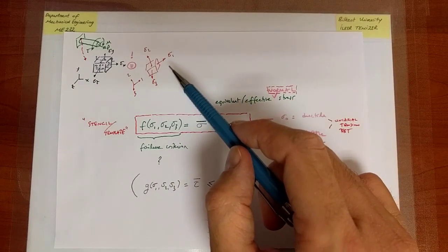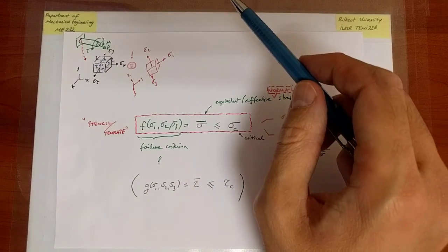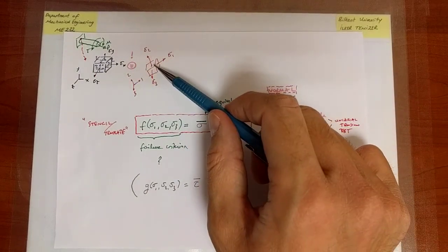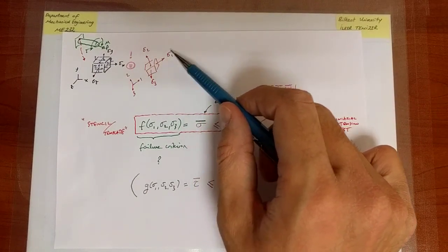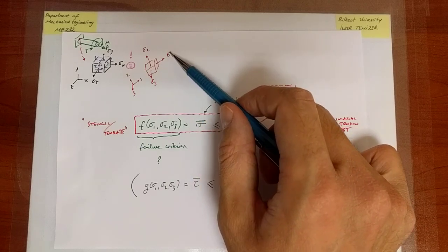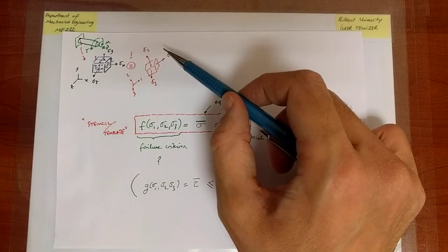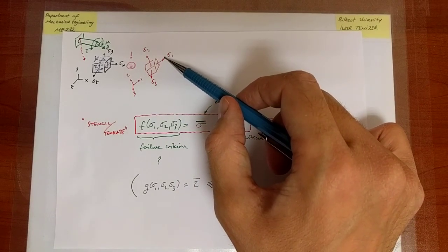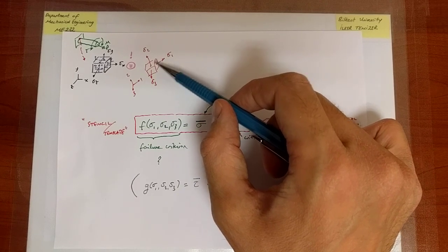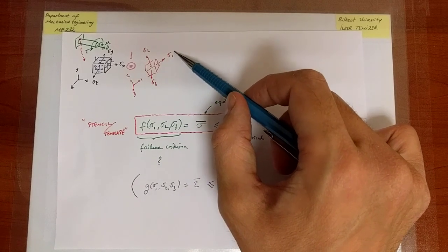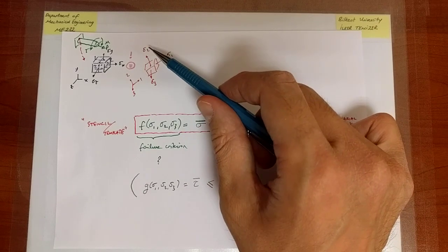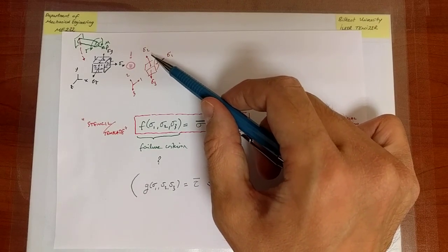And the material will fail because, let's say, the maximum normal stress you can apply is actually a certain value. So I only need to monitor the maximum normal stress. In this case, 100, 50, 30, 100 is the maximum one, and 100 is in that direction. Well, and then I try to decide whether failure will occur or not. Now, but I can imagine that in some cases, perhaps the orientation of that 100 is important. Perhaps if I apply to a material 100 MPa in that direction, it will fail, but in some other direction, if I apply 100, it will not fail.